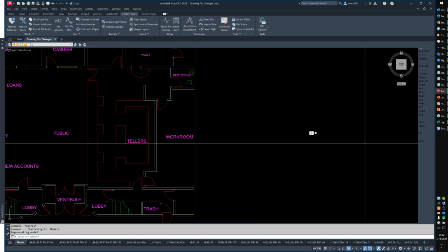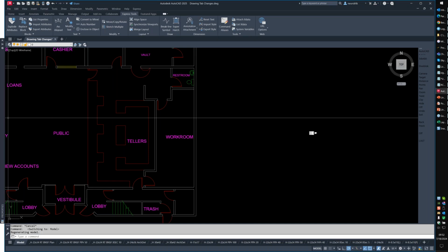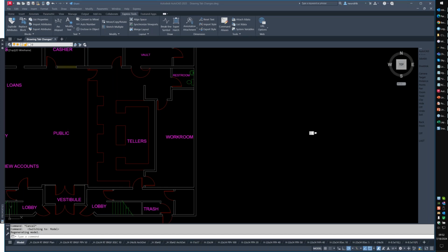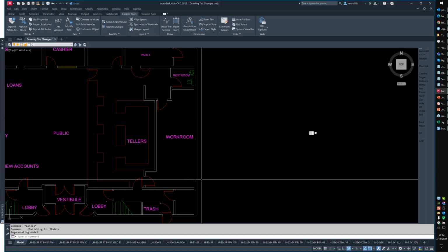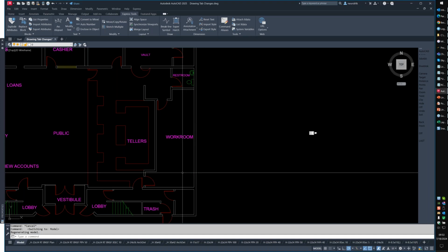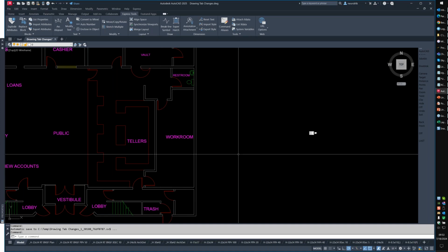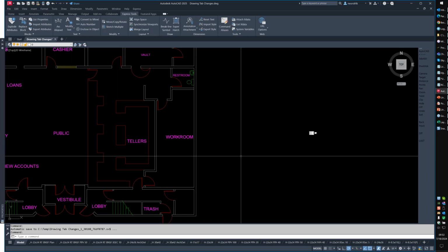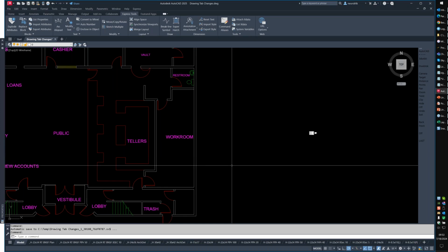Do you know how to change coordinates in CAD map to insert shape files from GPS information? All right. So Sue, if you're in basic AutoCAD, if you go through the GeoMap, you will never be geolocated correctly. Your best bet would be to move up to Map 3D, which you should have access to. Map 3D has a traditional AutoCAD style interface, just like this, a workspace. So you do have Map 3D. What you would do in Map 3D is type in MAPCSASSIGN to correctly assign a coordinate system, and then MAPIINSERT to import the shape file.